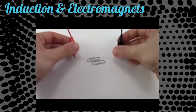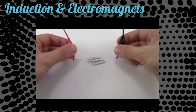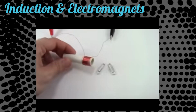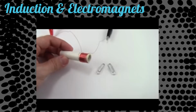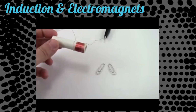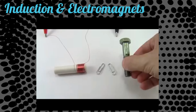However, the magnetic field around a single straight wire is very weak, not enough to pick up even one of these paper clips. You can make the magnetic field much stronger by wrapping the wire into a coil called a solenoid. This causes the fields around each individual turn of wire to add up to make a much stronger, more uniform magnetic field similar to that of a bar magnet like this. However, you'll see that this coil of wire is still too weak to pick up an individual paperclip. To make an electromagnet really strong, you need to add a ferromagnetic core like this iron bolt.